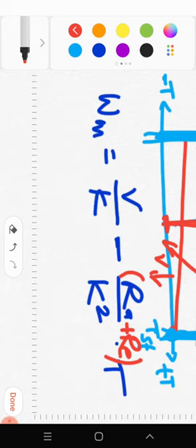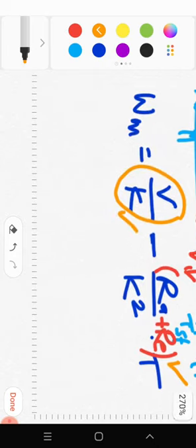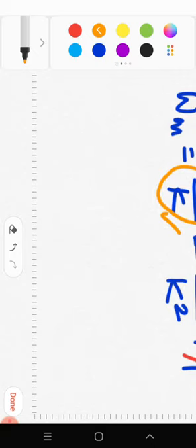So the y-intercept point remains unchanged, V by K. So this is the point in the y-axis through which the characteristic cuts the y-axis, isn't it? So that point remains the same, and whatever are the values of the external resistance, those decide the slope of the characteristic. So in this case, it will be multiple characteristics passing through this point, having multiple slopes.